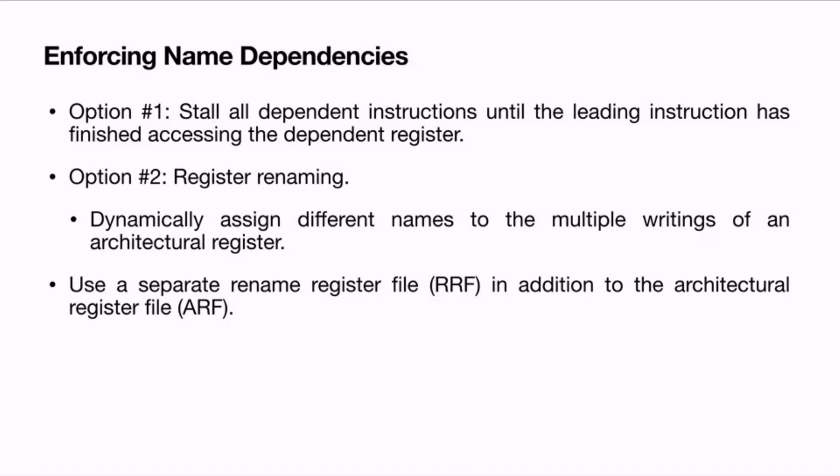And typically you can have rename registers, some 60-70 registers will be there, and they can be used so that you can have more in-flight instructions in this pipeline. Typically, if you see any of these Intel processors, you will have around 100 to 120 in-flight instructions in different stages of the pipeline. When you have a 16-stage or 17-stage pipeline, you can have a large number of in-flight instructions. That is possible because you have a large number of rename registers, and you can use that to rename the architectural registers. And now, how do we map this architectural register with the rename register file?